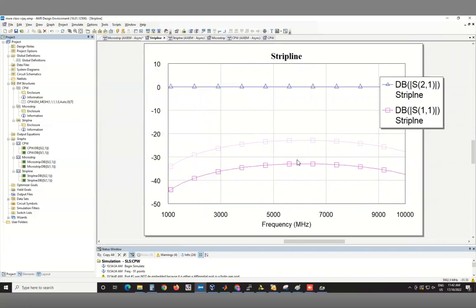So this is again something you will notice, that the numbers given from TX line might not exactly match with EM structure simulation. That said, 443. Now clearly 500 is further away from 443 than 450, which we had tried. But here it seems to indicate that 500 is better. But it should not be too far off.